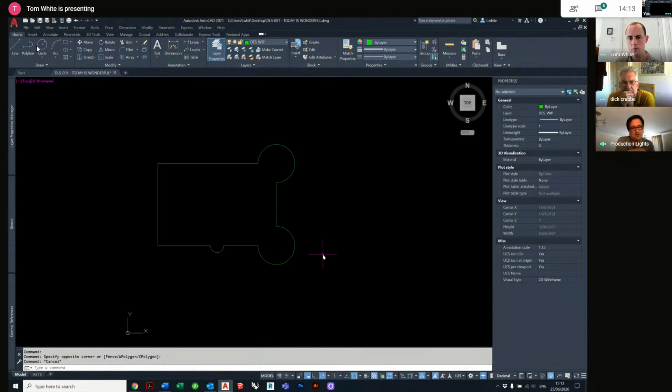And I think very quickly, as you go on, explaining about closing a polyline is really good for hatches when we come on to it, and I think that's where a lot of people get unstuck with hatches and filling in. So just the thought process. Dom, it was interesting that you ran through what we're going to talk about, because they're all very much linked to one another, like you allude to. To do a 3D solid in comparison to a 3D mesh, you have to close a polyline, or you need to join a polyline.